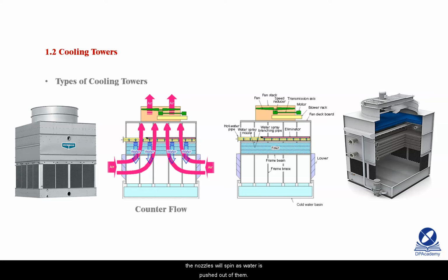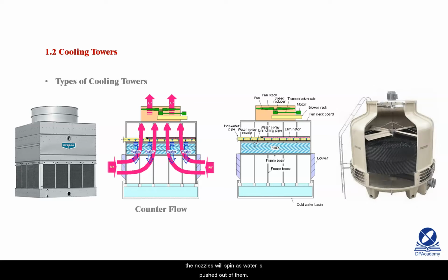Again, you can see the components in the cut section. And for the cut section of the round cross-flow cooling tower, you can see the same components. However, the nozzles will spin as water is pushed out of them. Thus, water is evenly distributed across the filler.